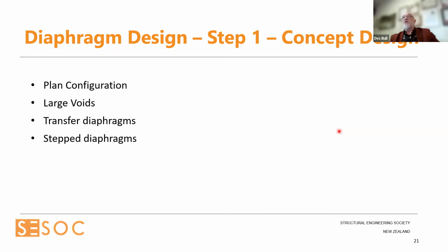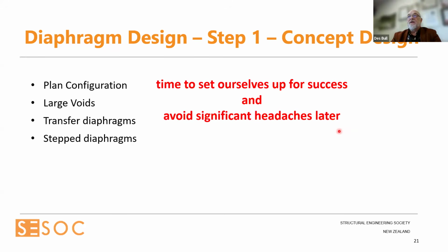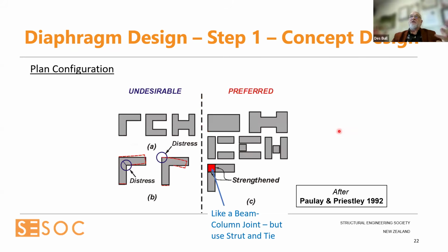In step 1, the concept design, what we're worrying about is our plan configuration, what's the shape of the floors, where are the large voids, do we have any transfer diaphragms, and the other one was, do we have stepped diaphragms, vertical stepping. This is the time to set ourselves up for success and avoid significant headaches later. And you'll see why as we go through the slides. So this is the concept stage.